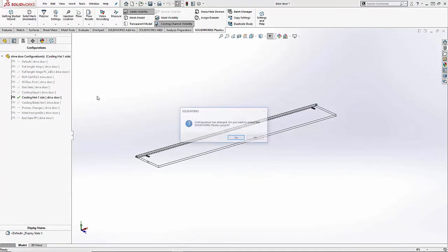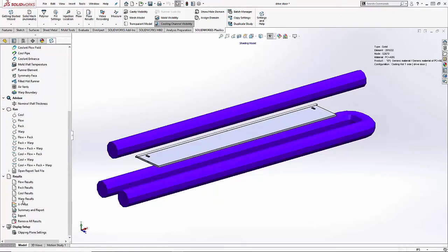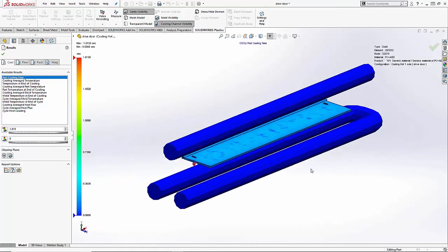My next study I ran, I wanted to show the effects of having your mold temperature different from one side to the other. So you can also control the way a part warps with your mold temperatures. If one side of your mold is hotter than the other, you've got non-uniform mold shrinkage. The part will tend to try to shrink toward the hotter side of the mold. So during your process, sometimes an injection molding setup person will set the mold temperature on one side of the mold hotter than the other just to have it shrink the other direction. So that's what I've done in this case.